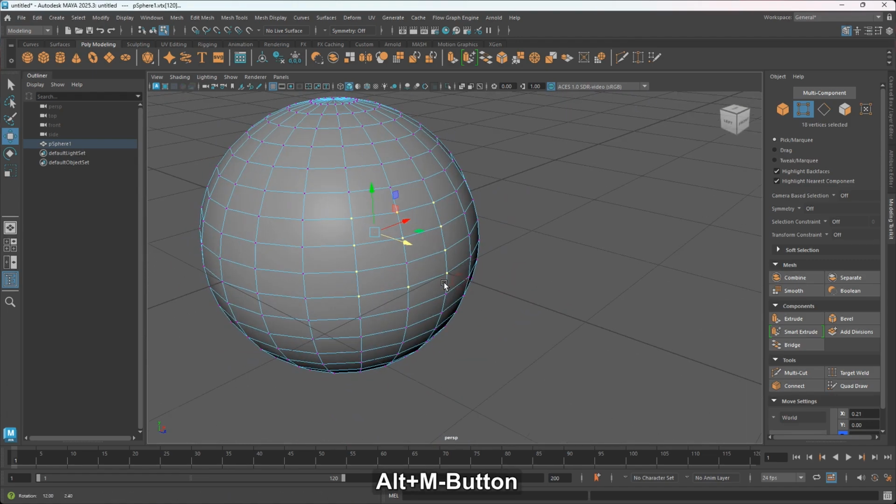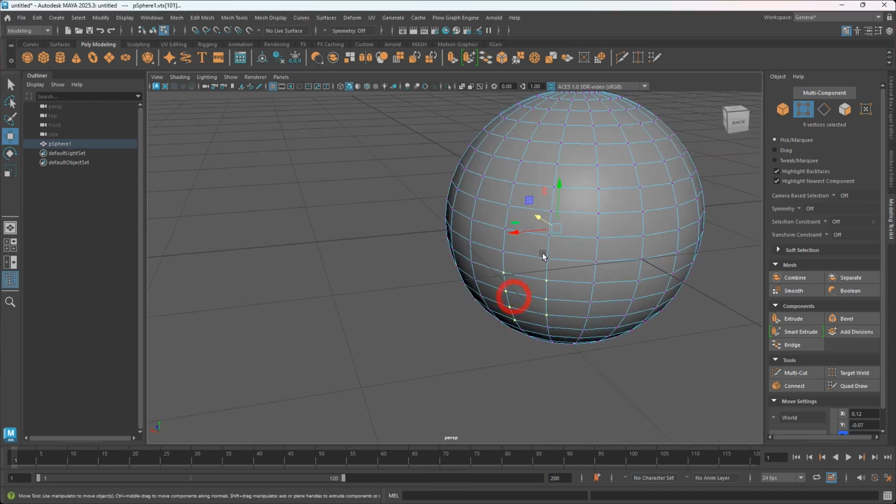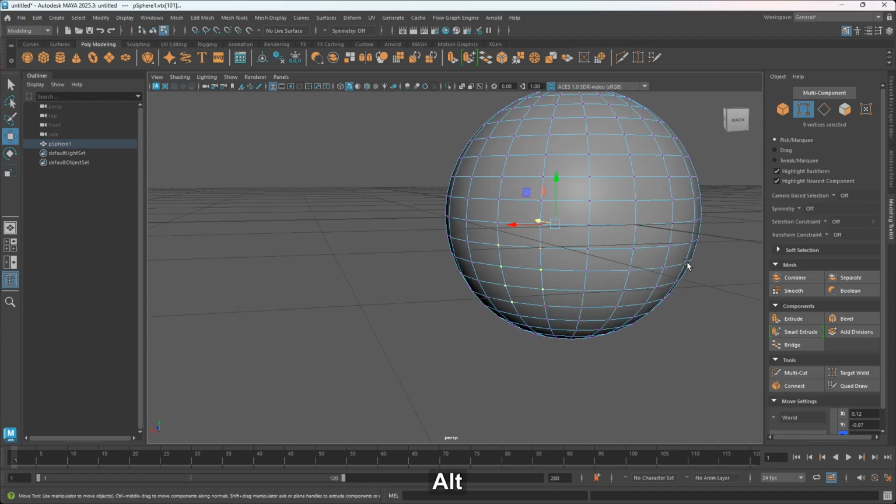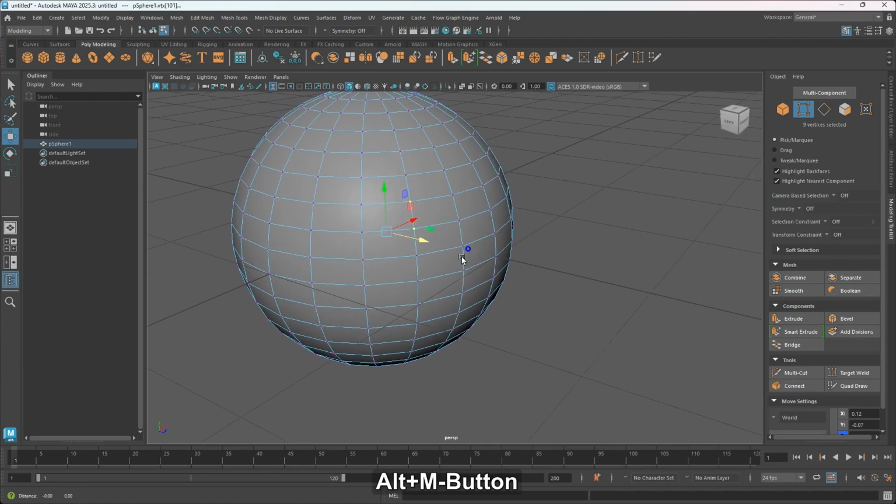Now, if you encounter this, you can just go over to your modeling toolkit. This is what I told you guys in one of the lessons before, that I'm not going to explain the modeling toolkit in that lesson, because as we keep working, we are going to make use of it, and I am going to explain some things for you as we keep going. Because I make use of the box selection, you can see that I have all that vertex selected from the back of my sphere.